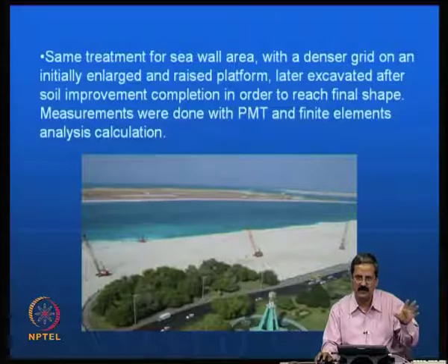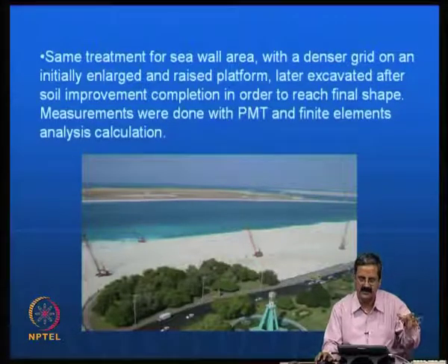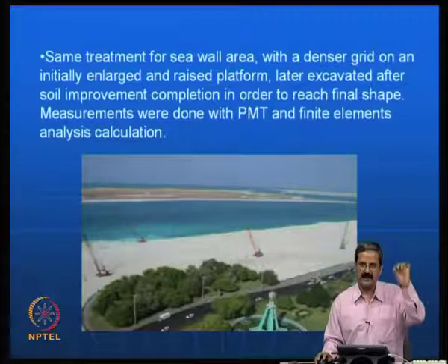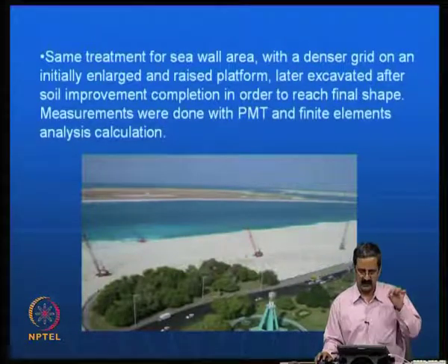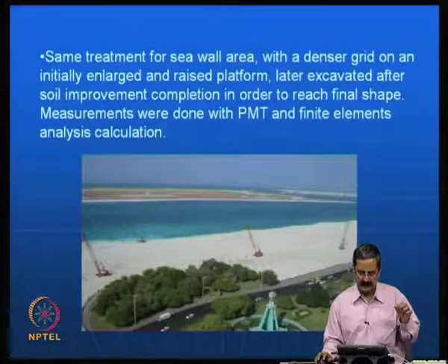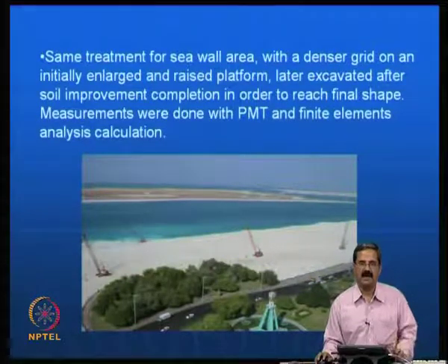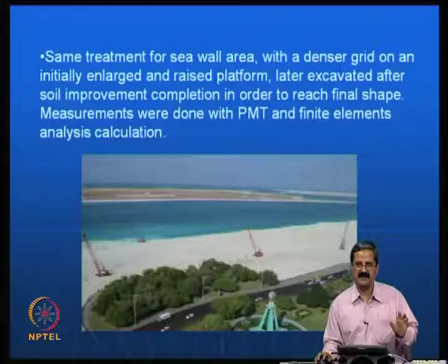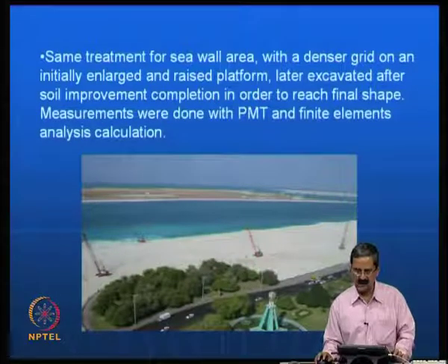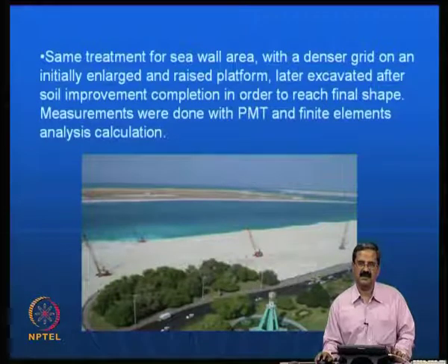For example, using even finite element calculations, you can simulate the whole structure at the top of the soil and then understand where the stresses are going. If the stresses reach a very soft area, then the problem is that it could lead to a lot of settlements, and one should really optimize and make sure those settlements do not occur. These are some of the issues that one needs to understand to see that dynamic compaction is done in a proper way.